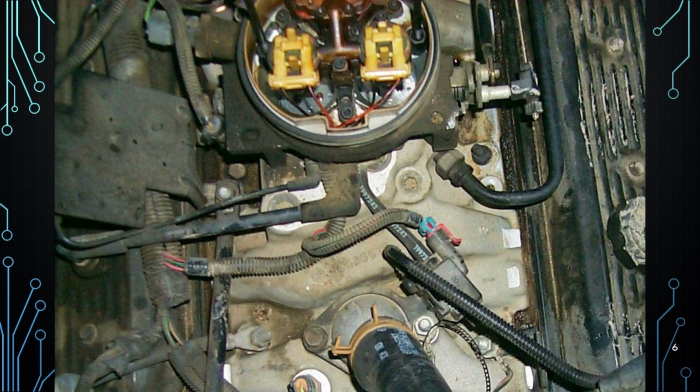That black device with an electrical connector and vacuum hoses is likely a purge solenoid. For the evaporative emission system, the purge solenoid controls when stored fuel vapors in the charcoal canister are drawn into the engine to be burned. The solenoid is commanded electrically, opening or closing that vacuum path.